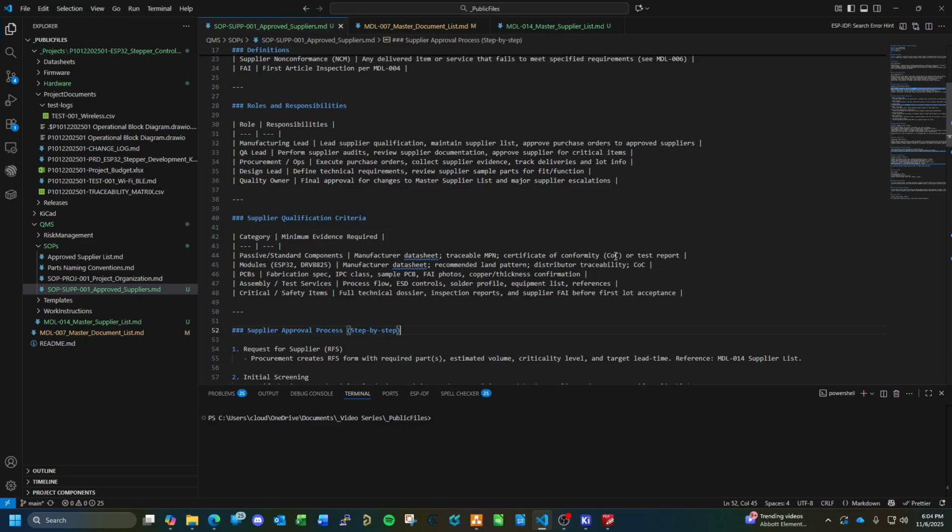Amazon's good for getting development kits and test parts, but nothing against Amazon, I would not use them as a supplier for a manufacturing house. I'd be okay with it for things like M3, M4 metric screws and hardware. But if you're talking chips, ICs, other parts, no. I go with reputable vendors like Mouser, DigiKey, Arrow Electronics, Newark Electronics, Future Electronics. Go with a reputable vendor that's been established in the industry for a long time.